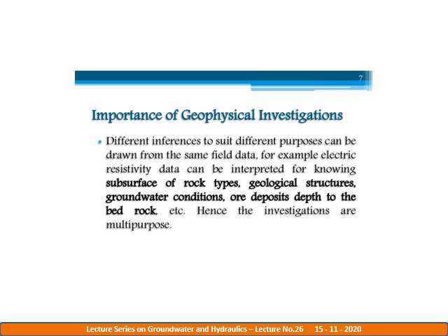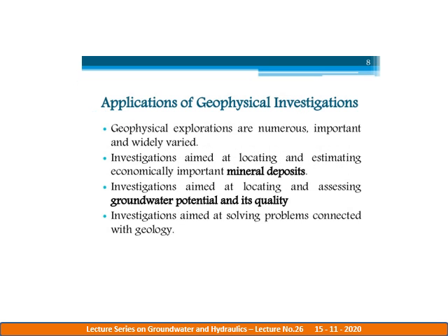Different inferences to suit different purposes can be drawn from the same field data. For example, electric resistivity data can be interpreted to know subsurface rock types, geological structures, groundwater condition, ore deposits, depth to the bedrock, etc. Hence, the investigations are multipurpose.